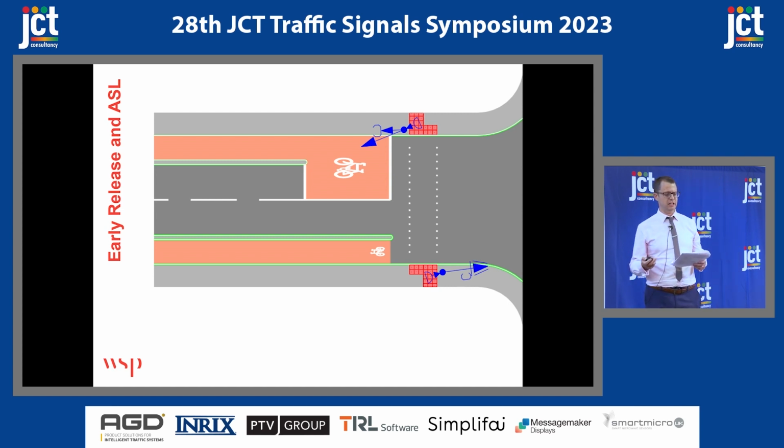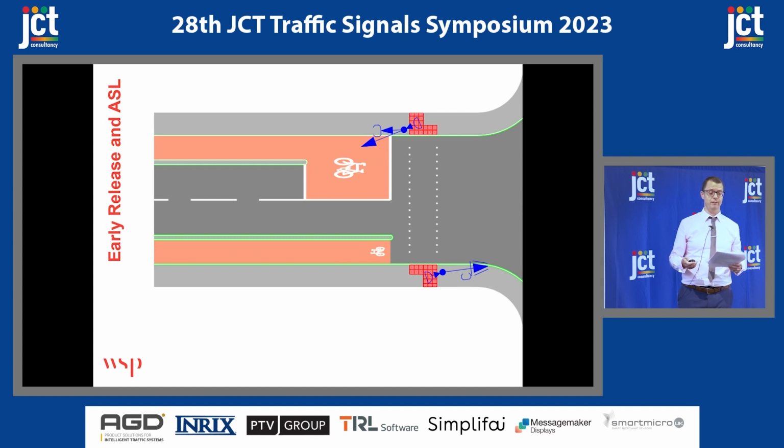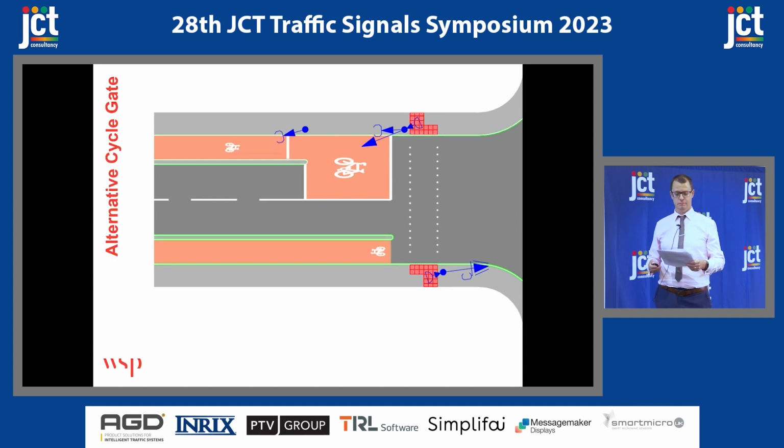As mentioned earlier, the key issue with ASLs, even with an early release, was that cyclists who arrive while other traffic is at green are brought into conflict with that traffic. Now, the best solutions are often the simplest, and with that very much in mind, after great thought and deliberation, what I came up with was this. I just added a separate signal and a stop line for the cycle lane prior to the ASL to stop cyclists from reaching the conflict point at times when it would be potentially dangerous for them to do so.